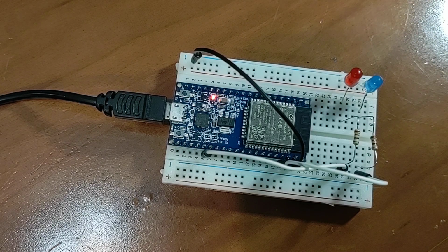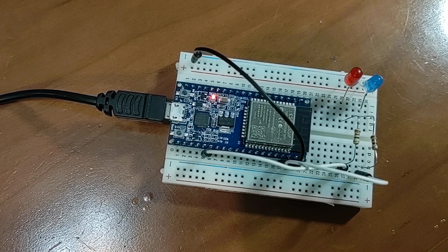So I have two 220 ohm resistors that the current goes through before it goes to the LED. The reason we need a 220 ohm resistor for an LED is because even at 3.3 volts, once an LED is forward biased and conducting current, it does so with very little resistance. So if you just run an LED with a battery or a microcontroller without an inline resistor, you're basically creating a short to ground from power. We don't want that, because we don't want an overcurrent issue to happen with our board.